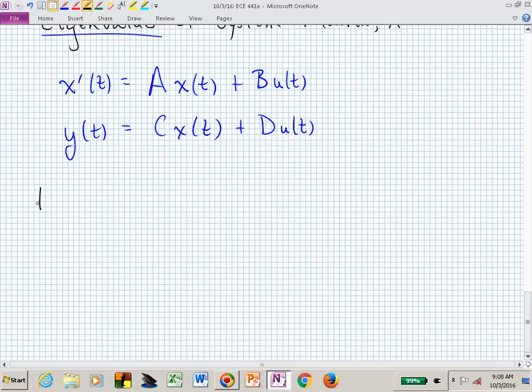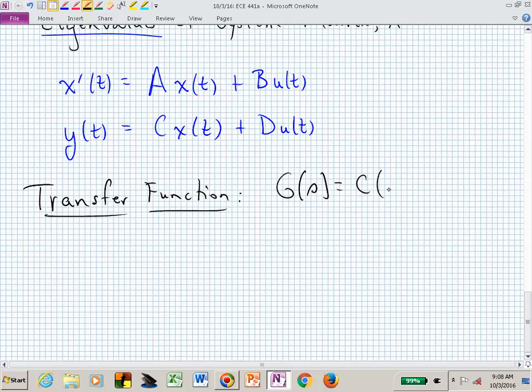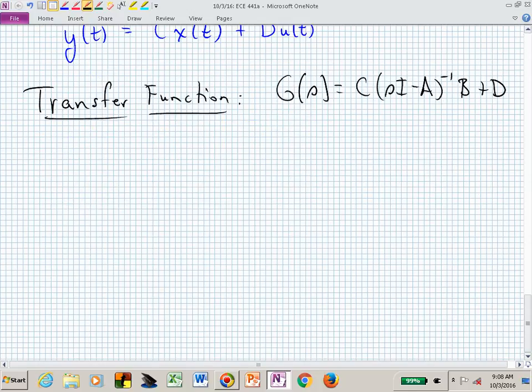Now we could do chair number 1 to give us the transfer function. If somebody gives us A, B, C, and D, what can we write down immediately for the expression for the transfer function? If we include the D, it's hanging out there by itself as the direct feed-through. Now, what I want to focus on is this sI minus A inverse piece.